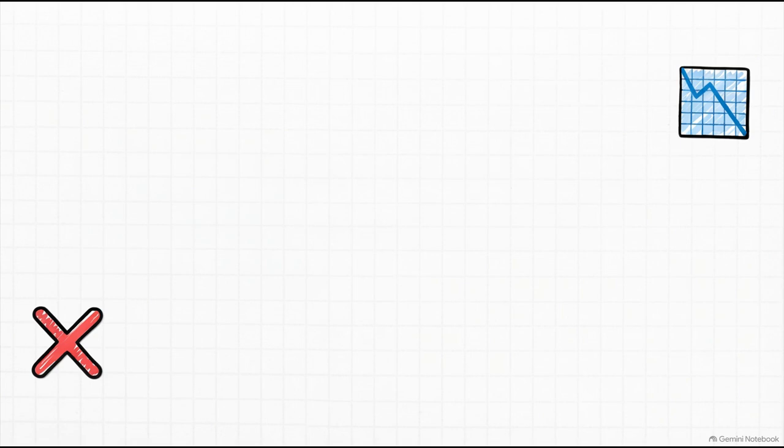Your required action is to flag that the requirement is not satisfied. Look, even though the average looks fantastic, you cannot approve the work because that single core criterion failed. Both rules matter, and a failure on one individual core means the acceptance criteria have not been met.